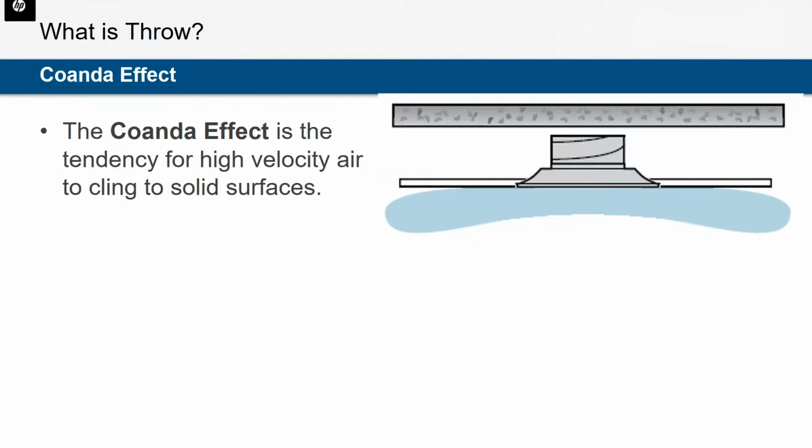This gets into boundary layer theory if you want to look into the engineering. Essentially, high velocity air is sticky. It likes to stick to solid surfaces, and that means that less of the boundary of the air jet is exposed to the rest of the room, and thus there is less friction between the air jet and the otherwise low velocity air.